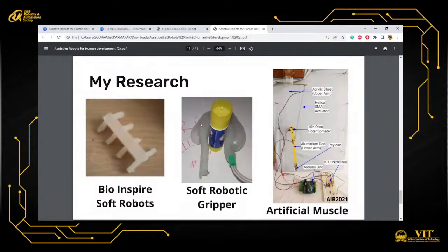But for pneumatically actuated grippers, the advantage is that they're not like the rigid body robotic grippers or end effectors, which are completely on or completely off, or opening or closing 90 degrees or 100, 180 or whatever. It's not like that. Whatever your object is, according to its size, it can insert it, basically cover it or grasp it like that. So that's a great thing.